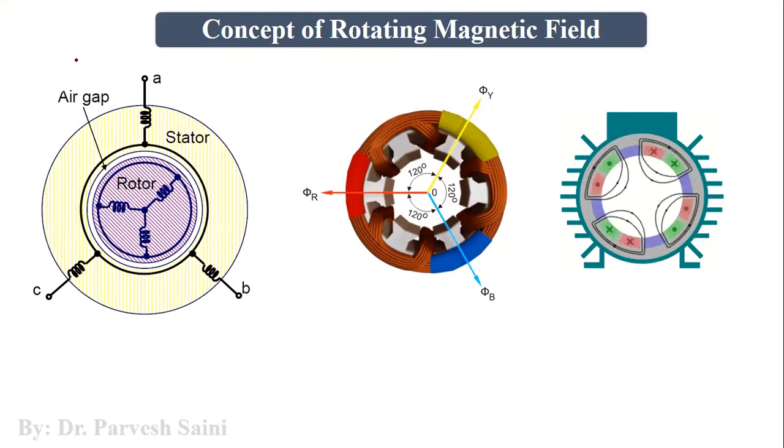as you know, a three-phase induction motor has two three-phase windings. One is on the stator and one is on the rotor. The rotor can be of cage type, or it could be a wound rotor three-phase induction motor, right? In both cases, we have three-phase winding on stator as well as rotor. The connection of three-phase winding could be a star connection or delta connection, depending upon the rating of the three-phase induction motor or the requirement, as far as the application is concerned, right?